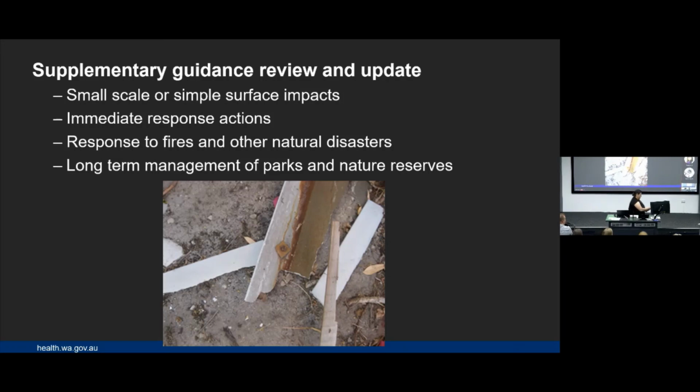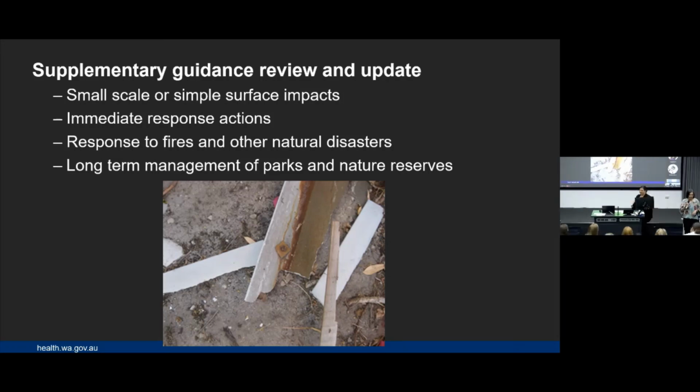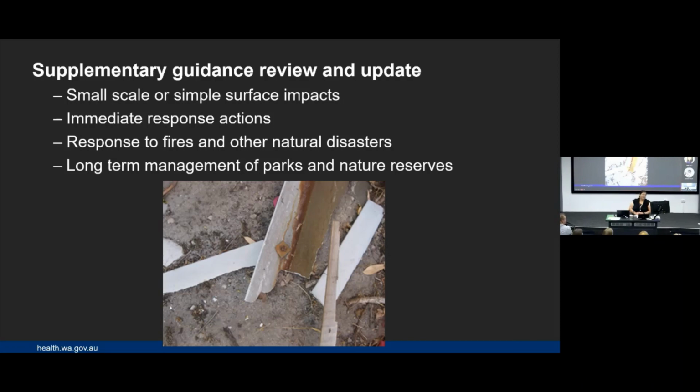As far as removal works? Okay. Right. As I mentioned, I haven't seen the finalised draft. I'm not aware that WorkSafe needs to be notified of soil remediation work. I think it would be considered removal work, like I mentioned, Class A, Class B work. At the moment, notification of that work is only related to unrestricted or friable removal by Class A's. Under the new legislation, notification of removal work for both Class A and Class B will be required.